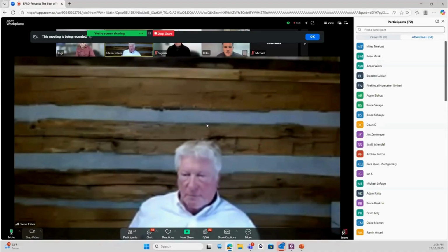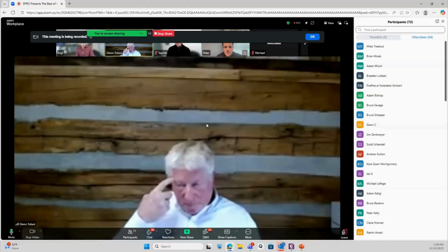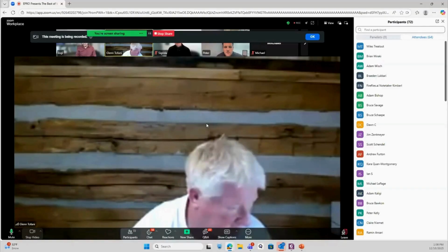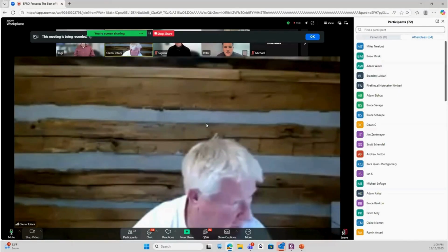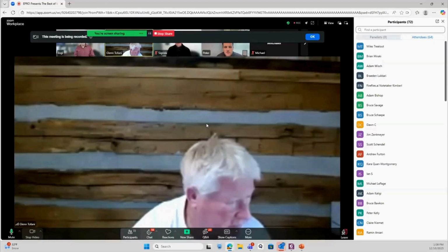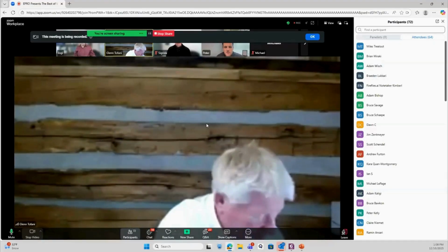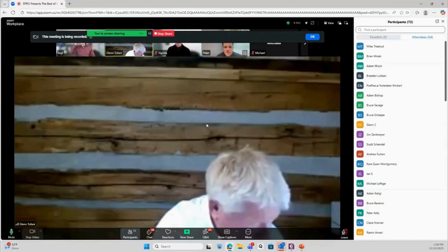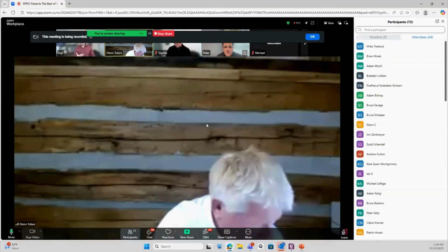So yes, this model is going to give out a system curve, and every engineer uses that to design and appropriately size the fan. So for new construction, where we are not able to go out and do pilot testing ahead of time, you use this mathematical model to come up with the system curve. So the answer is yes.